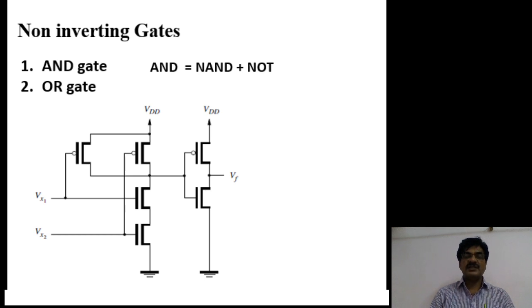With reference to this AND gate, you plot the functional table. The functional table includes number of input columns, number of transistors, and only one output column. For each and every input binary combination, first of all you represent the state of each and every transistor.